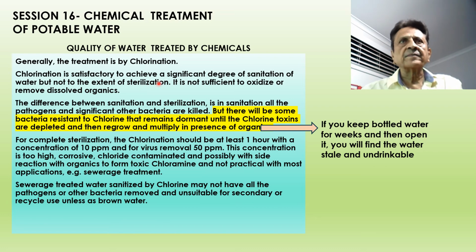The difference between sanitation and sterilization is that in the case of sanitation, there might be small amounts of bacteria which are not harmful but will not have any harmful bacteria or pathogens. But in the case of sterilization, there will be no pathogens and no bacteria, and that sterilized water is completely free of bacteria and virus as well as